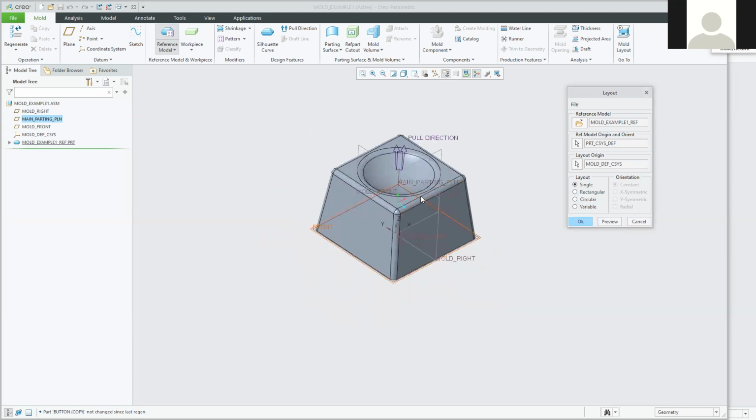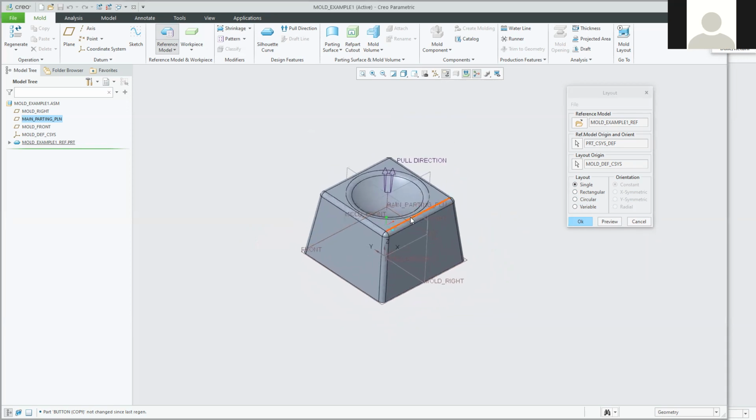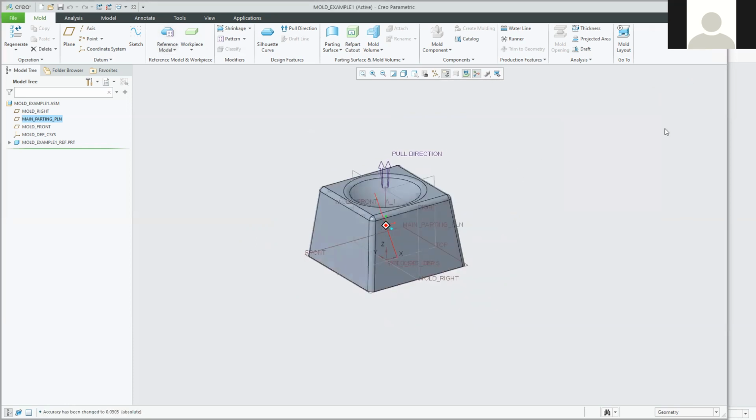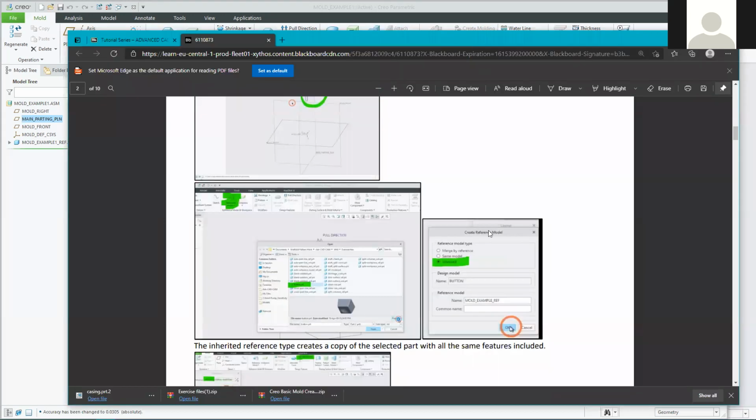We're just going to create a single mold cavity that creates a single part for every injection cycle that we're going to run. So we'll click on OK. Cavity layout is done. So we click on OK up there as well. So we brought our reference model in. So let's move on to the next step.